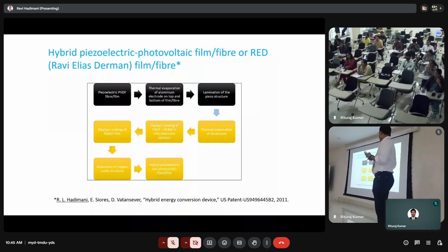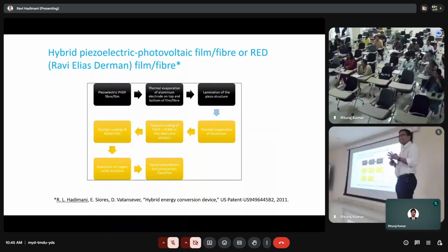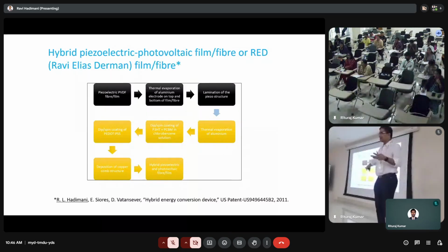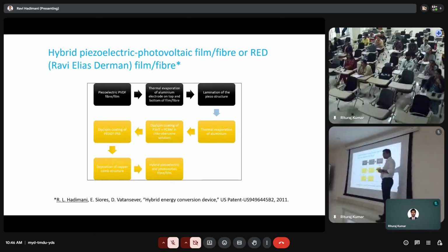Okay, so I had no background in photovoltaics, and I had to do the literature search and come up with one type called organic photovoltaic cell. Organic photovoltaic cell was easy because you just coat different organic compounds, and by doing that, you make a photosensitive layer, and that generates additional charge carriers when the light hits it. And then you deposit electrodes on top of it to extract these electrons, which means extract charge, which means get voltage out of it.